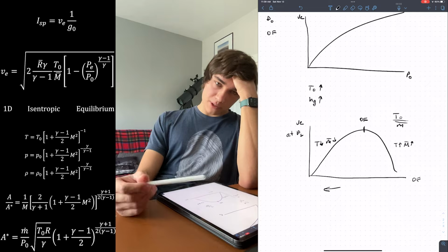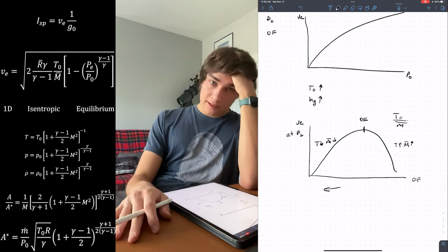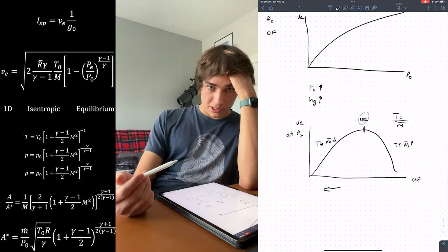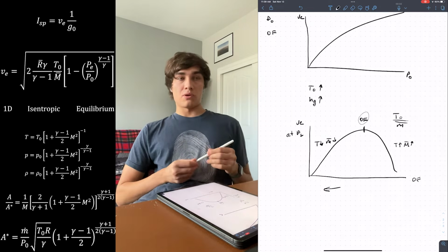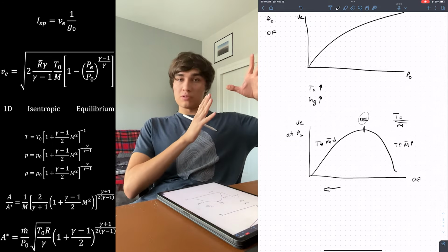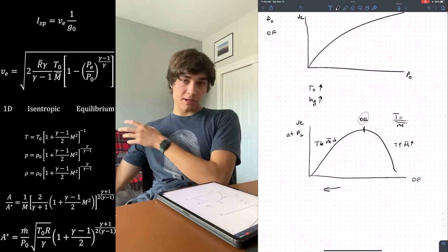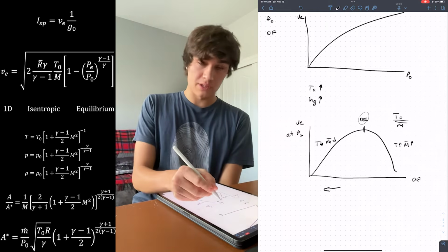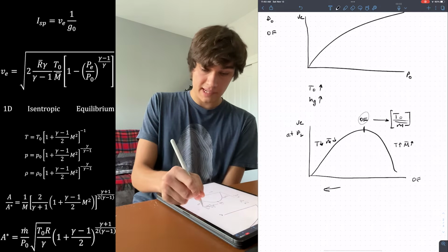Now here's the problem. I'm talking about an ideal OF ratio. Don't think about it as related to some stoichiometric mixture. You will actually hear this idealized OF be referred to as a stoichiometric oxidizer fuel ratio by some people in the industry. But this term is confusing because it does not describe a stoichiometric mix in terms of this many molecules of oxidizer to this many molecules of fuel that yields some combustion products. You really should only think of the ideal oxidizer fuel ratio as where this ratio is maximized.